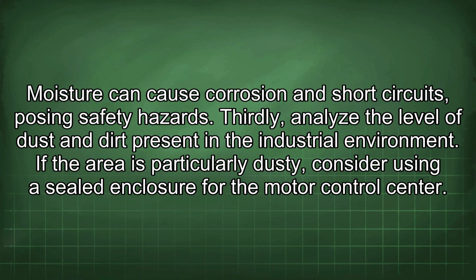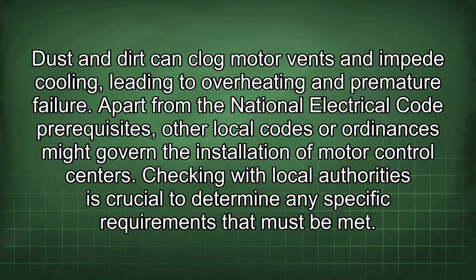Thirdly, analyze the level of dust and dirt present in the industrial environment. If the area is particularly dusty, consider using a sealed enclosure for the motor control center. Dust and dirt can clog motor vents and impede cooling, leading to overheating and premature failure.